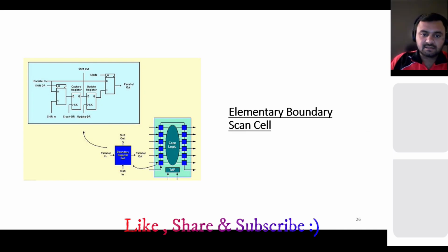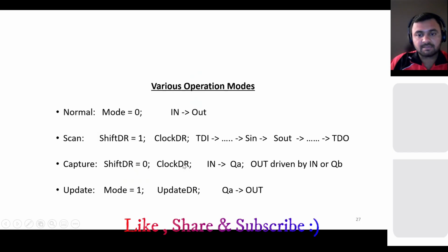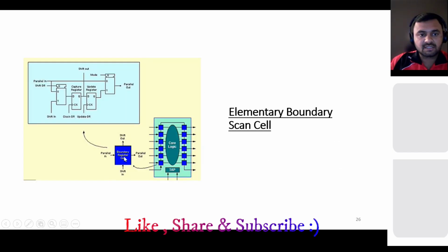And the boundary scan cell, as I told, you have the logic, you have a TAP, and then the boundary scan is just a wrap around. So this is your boundary scan, and basically it looks like this. This is just one example of a boundary scan cell, I think it's BC cell 1. And there are 7 different BC cells, because you have input, you have output, and some of the pads may have in-out. So for each individual pad, you need a different kind of cell. So you need BC1, BC2, BC3 till BC7, we have 7 different boundary scan cells.